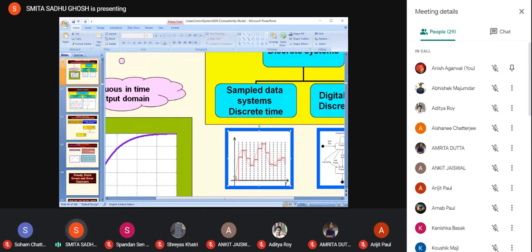We use what is called a hold. You will learn that in some other course. And for example, over here at 0.5 second, the impulse value was this much, but that has been held during that interval, till the next instant has arrived. So that is possible, but nevertheless the discrete values were obtained for these discrete instants only to start off with, but not between those intervals.